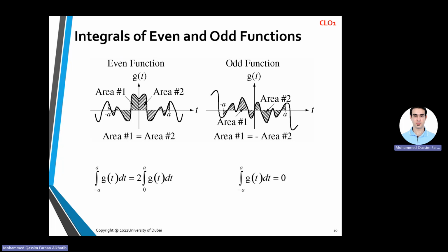In calculus, you calculated areas, right? The areas that are under the x-axis, you multiply by a -1. You give it the absolute value because physically area should be positive. Here, we are not limited by physical constraints. We're not talking about areas. It's just integration. Now, when you integrate an odd signal for a full period, like the sine signal, integration of negative pi to pi sine of t dt, this is an odd signal, and I'm integrating over a full period, that's going to be 0.